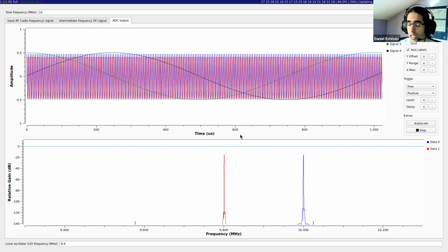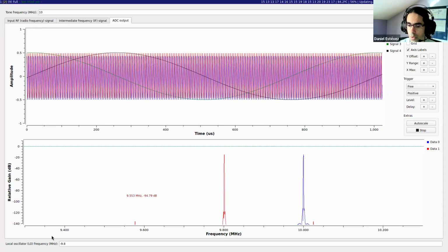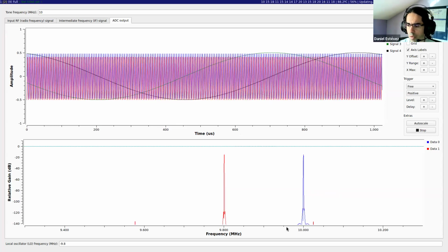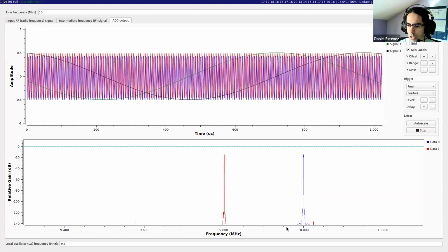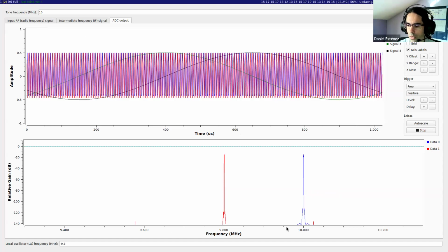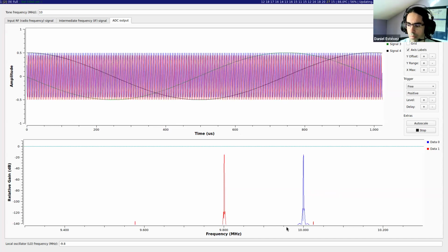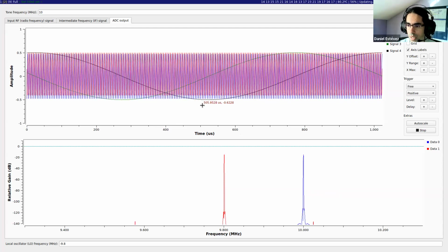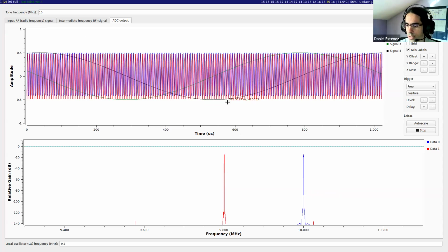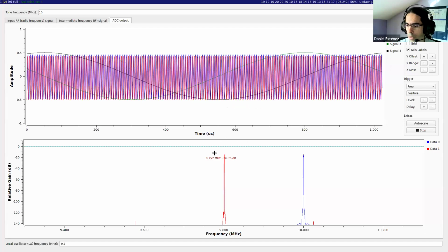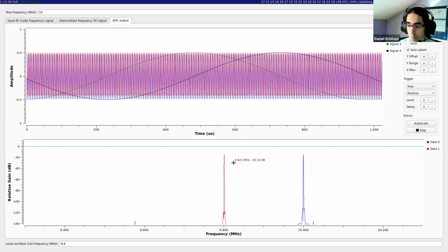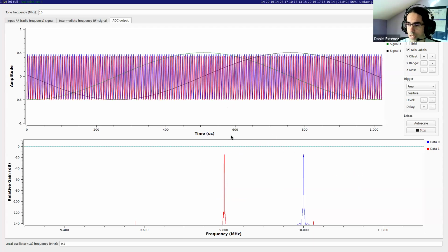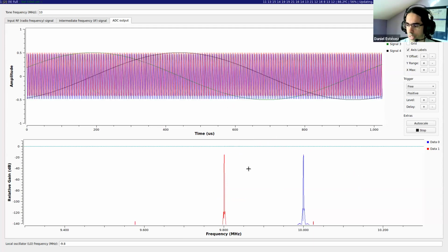And if you remember GQRX, it was showing us the proper frequency axis. So when we tuned to some FM radio station at 98 megahertz, it showed 98 megahertz on the frequency axis rather than -2 or whatever. But the frequency for the samples we are getting on the USB connection is -2 or -1 or +1 or something small because it has been down converted. The technical term is down converted or shifted down in frequency.